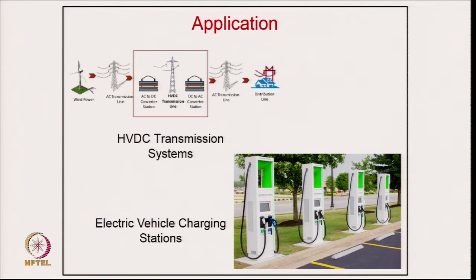Moreover, it does not draw harmonics and there is no need for bulky passive filters. You require only a very small ripple filter, similar to what we discussed already for voltage source converters. So, the new breed of HVDC systems goes by different names: we call it HVDC Light or HVDC Plus. The industry has put these converters, which have good power quality without filters, with bidirectional power flow in HVDC systems.